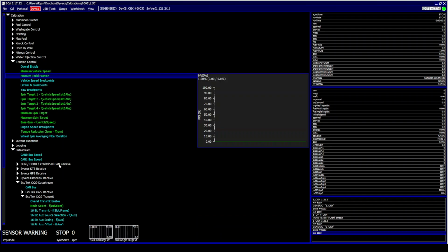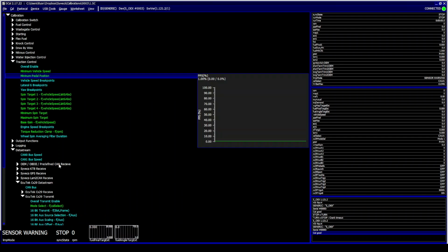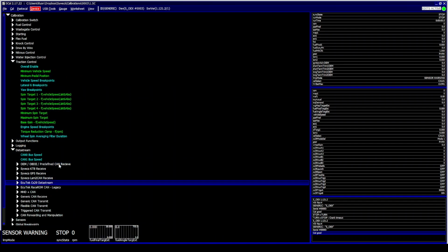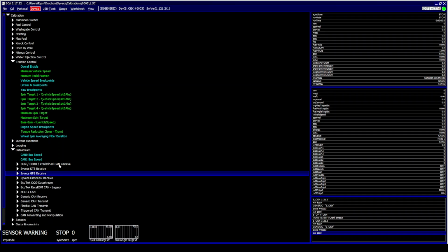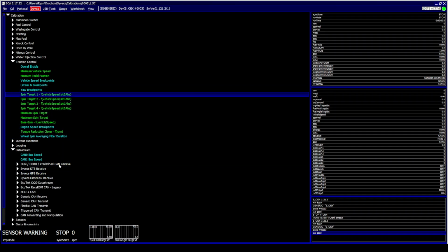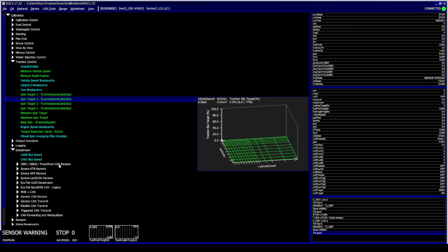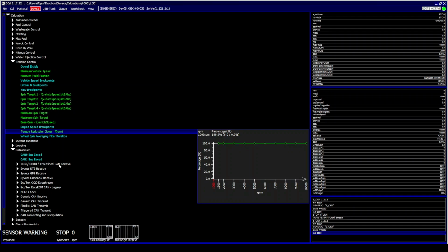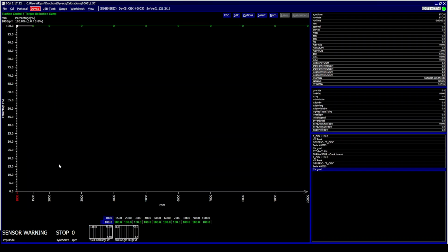So you can do all of your traction control calculations for your slip targets. You can also link in a GPS sensor. So you could go into here and enable the vehicle speed to come from GPS. You could receive the Syvecs GPS here, and on a four-wheel drive car you've then got a solid ground speed, and you can then pick up the four-wheel speeds to adjust your slip targets and torque reduction clamps.